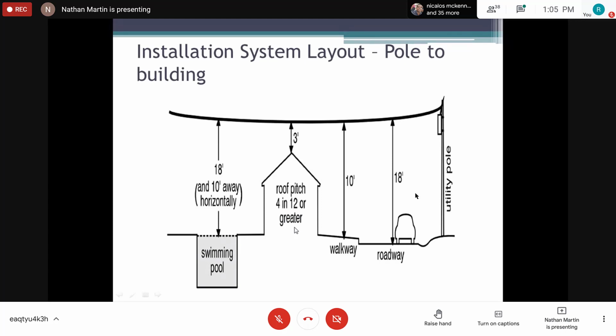So you realize that for a flat roof, this measurement will be different because this is for the pitch roof. If the roof was flat, we're talking about this distance that will be from here would be added to the 3 feet for your slab roof and so forth, right? So that's really for protection purposes because on a pitch roof, water will not settle. However, on a flat roof, you may have water settling if it was actually bordered around. All right?